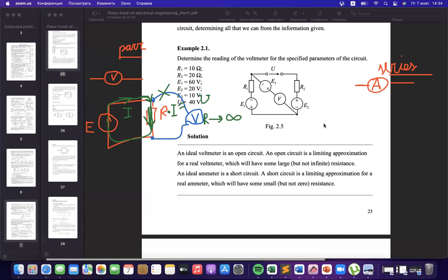That is a completely opposite situation for amperemeter. Amperemeter should measure current. It is connected serial. And the current in this circle flows directly through the amperemeter. And this amperemeter also shouldn't decrease the value of current. The current without amperemeter and with amperemeter should be exactly the same.